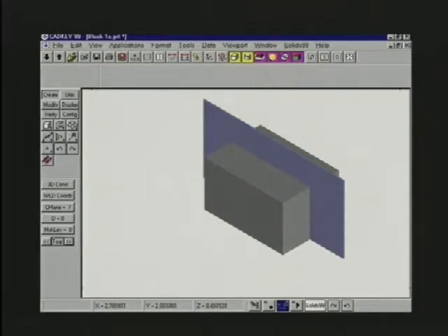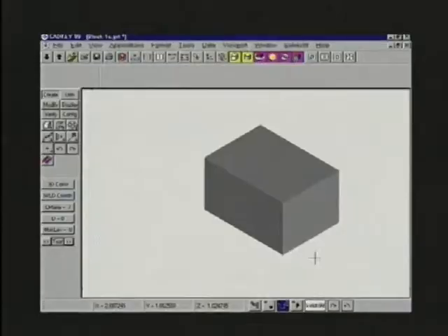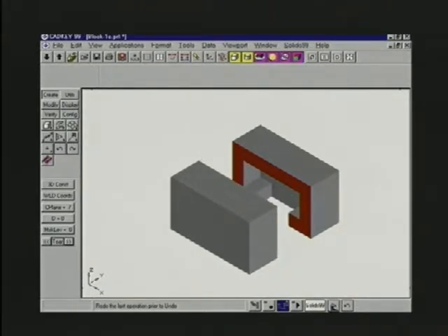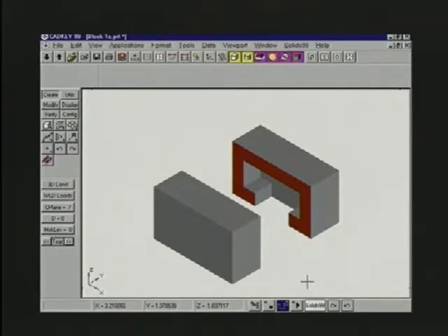Now you see how this is cutting all the way across that block again. Now that I've used that cutting plane to pretend to slice that object, let me move the part between my view and the cutting plane away to reveal what's inside the object. Now again, you can see that I've colored in red the part of the object that was actually contacted by the imaginary, and remember these are imaginary, cutting planes. And once we do that, you can see where the material is at the point where it was cut, and you can also see back into the object to see what's inside behind the cutting plane. It's kind of fun to put this back together, isn't it?